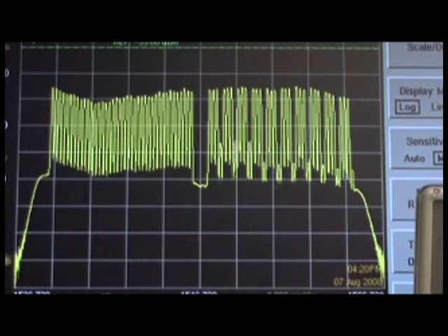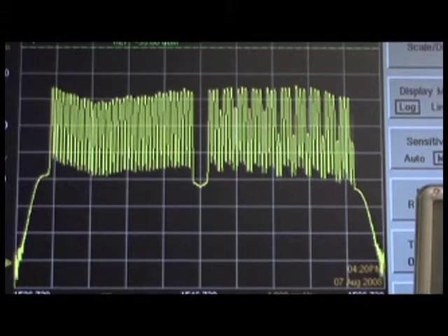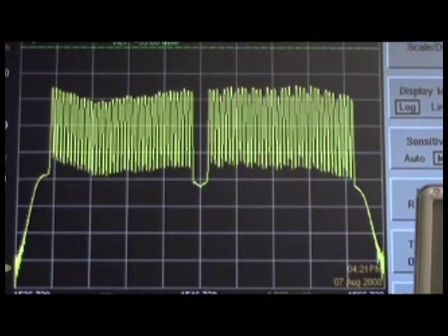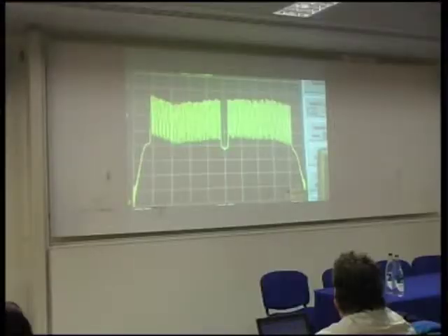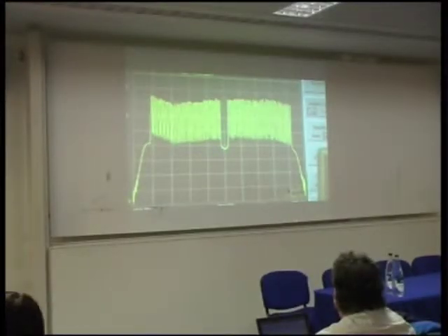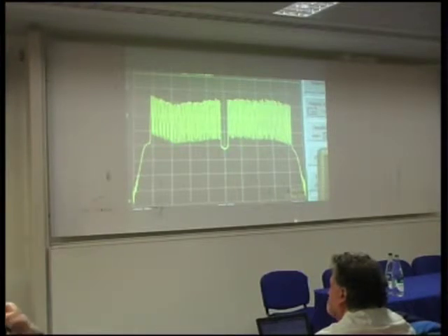Now, they come up a little bit hesitantly. That's called power balancing, and the reason for that is that this is a non-service interrupting operation. So it does not disrupt the existing waves that are on that fiber. So in 4 minutes, we've just added 100 gigabits of capacity. So next time your transmission guys say they can't have that till, you know, that London to Birmingham link for another 3 months, show them the video.